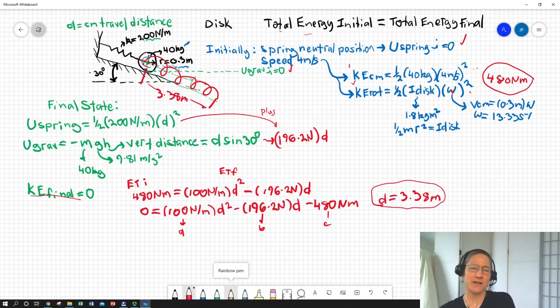So that's why I established the datum and then said, okay, if we're going to go with our starting point is 0 for gravitational potential energy, as we roll down slope, we're going to go to a negative energy state. I could have just as easily left the initial state as unknown and established 0 as the ending state. I would have a little bit different mathematics, but would have had a positive value for starting. So that is it for this problem. We'll have one more energy conservation problem, and that will be the end of our work energy rigid body discussions.